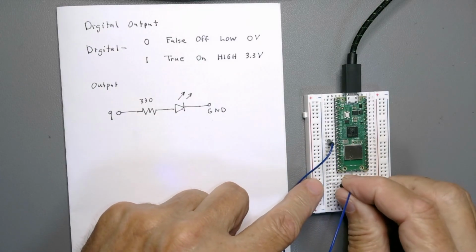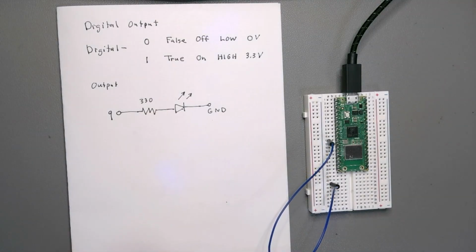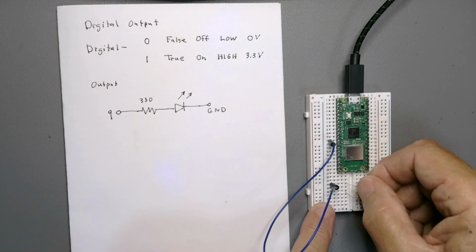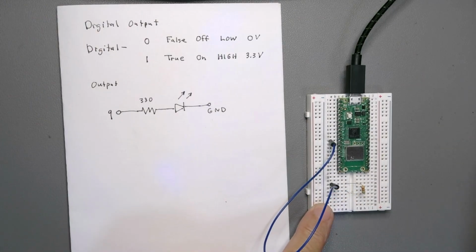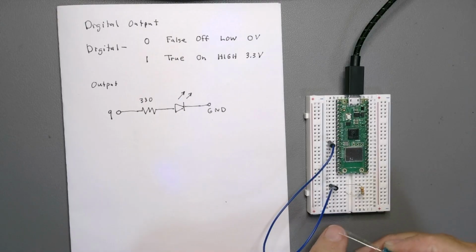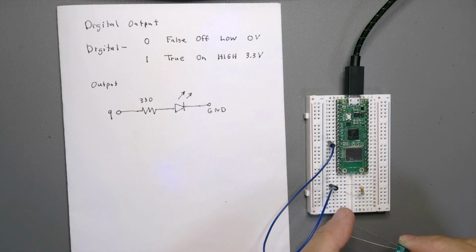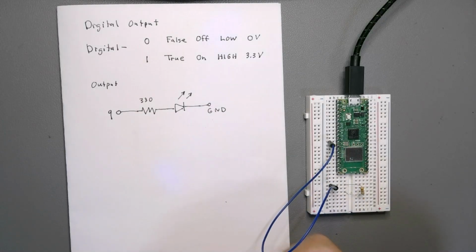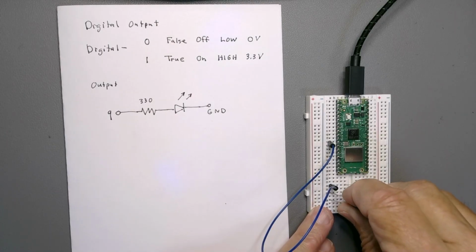And then I'm going to take it down here somewhere. Doesn't matter where. I'm going to plug in my resistor. Make sure that one of the legs of the resistor is in the same row as the jumper. And then the other, I'm going to bring in my LED, and it will go in the other end of the resistor. Make sure that's the long leg because it will be the closest to the pin that's actually going to go high and light up the LED. All right, so I'm going to go ahead and put this in here.